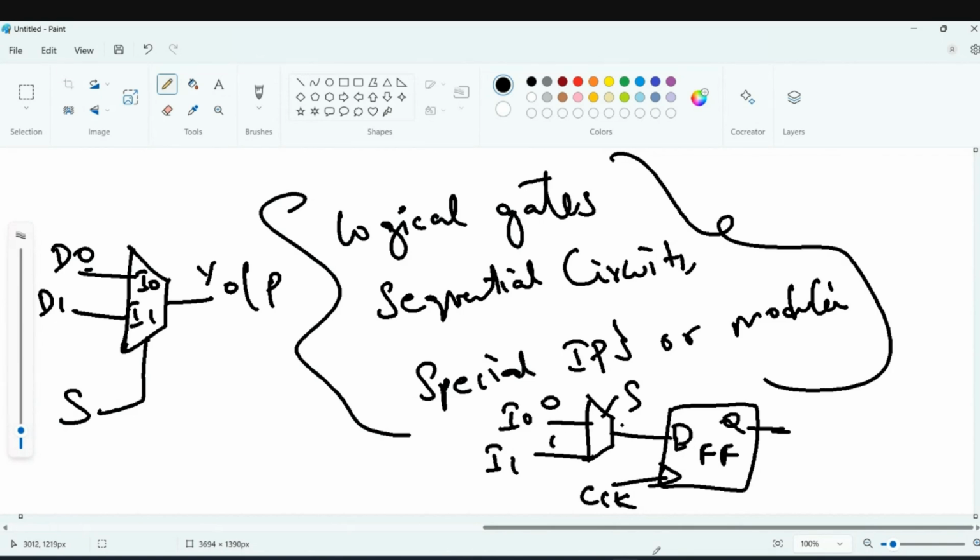So when you don't have this mux and two data inputs are connected directly to the D path of this particular flop, this is called a race condition. This is functionally wrong. We will not have any such conditions in real time. This race condition is from long back, when RTL engineers were not efficient. They used to write like this. We used to have a tri-state bus or different ways out to get rid of this.